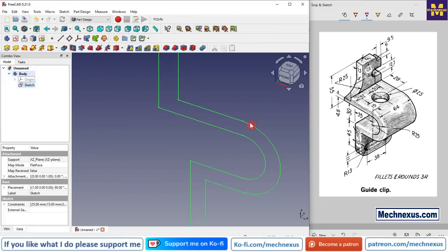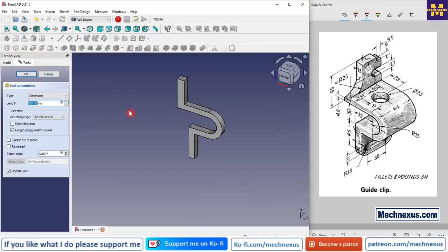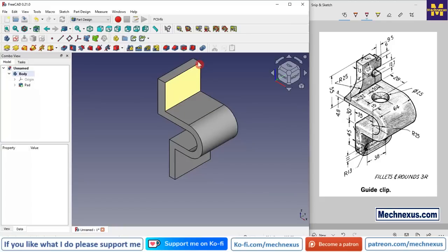We will come out of the sketch, and total extrusion length is 64. So click on the pad and click on the length, and also click on symmetric to the plane, switch to isometric and click on OK. So this is the pad feature which we have made.